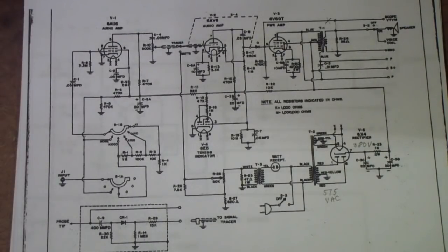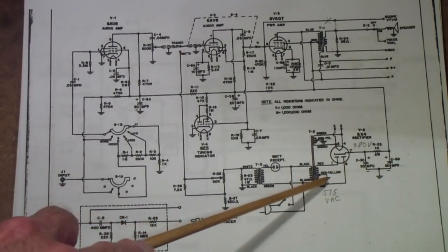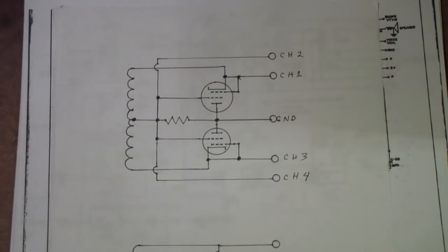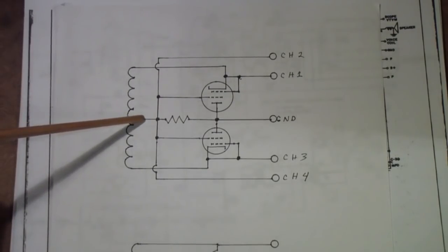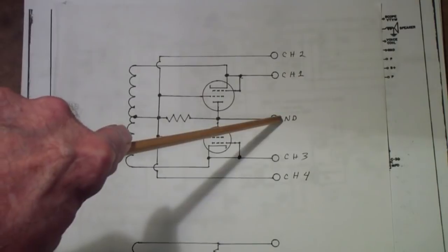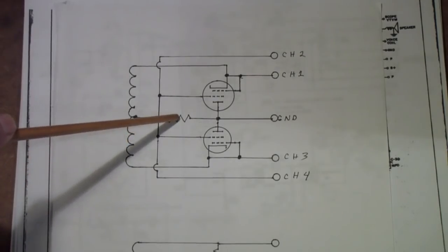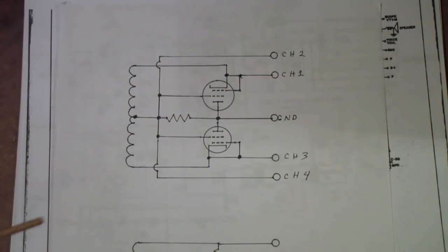Now you might ask, okay, well, that's all well and good, but what about isolation? Because one of the problems that you will notice here is that I'm hooking an AC signal to the ground of the oscilloscope. Now, yeah, it's separated by a resistor, but this is only 10 ohms. For that purpose, you need to make sure that this entire circuit is isolated from the AC line.